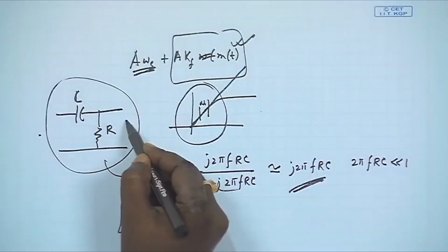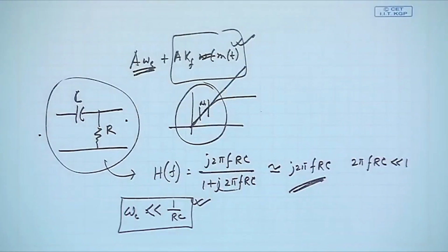Because this particular transfer function characteristics will be valid, that approximation also will be valid, and it will almost behave like an ideal low pass filter, high pass filter, ideal differentiator, right. And then if I just pass my signal through this, at the output I will get a differentiated output at that particular frequency. So, this is all that I will have to do. It is simple enough. All we will have to do is design our RC accordingly and then try to get a particular differentiation circuit.